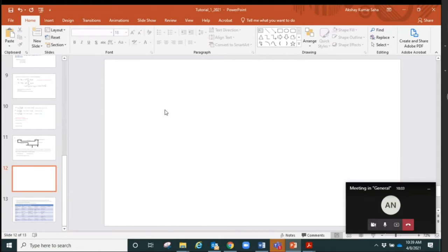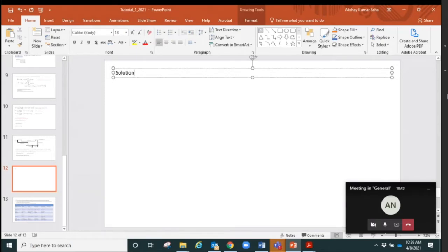So the admittances, just to make it generalized for you, we need to know the small y's: y10, y20 and y30, meaning those shunt admittances from each bus to ground. y30 means between bus 3 and ground.